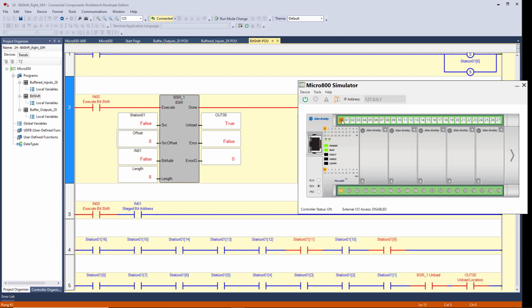Okay, the unload came on when we shifted 9. 9 didn't shift to 8. Okay, 9 shifted out. We unloaded the state of that element right there. We unloaded it into this bit down here. It didn't go from 9 to 8. So you see that you can have your length effectively anywhere in between the least significant and the most significant element of your array.